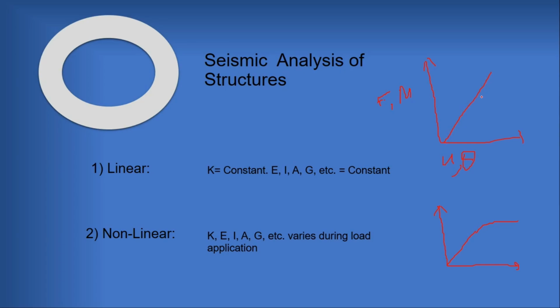But because of the linearity and constant slope, it will give some deformation during any kind of load. That's why it has some limitations. If we apply an unrealistic load, which might be extremely high, then it will give deformations that are unreasonable and extremely high. We have to manually check that the material has failed, because it will never predict material failure and element failure.